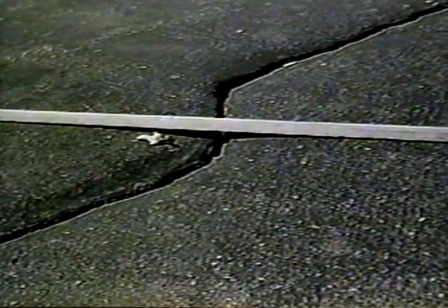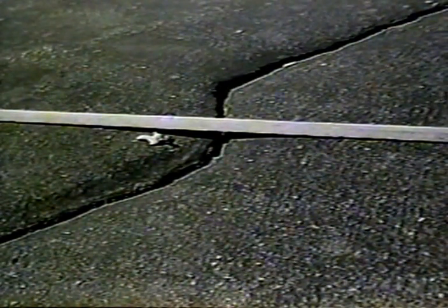Plus something else has happened here. You notice how the pavement has settled on either side of the crack? Well, if you get water down into these cracks and saturate the base and the subgrade, and then have traffic drive over it, what happens is the traffic forces some of this water up out of the crack, and with it comes part of the base and part of the subgrade. This is called pumping. And when you have this pumping action occur, it creates a small void under the crack, and you get this actual settlement. Frankly, you don't see this kind of settlement very often. I took this slide in a parking lot where the traffic was not all that heavy.